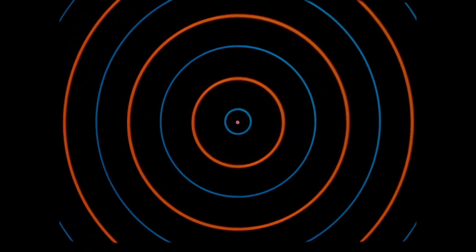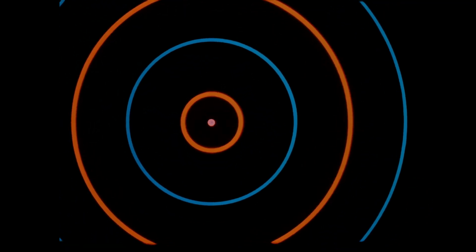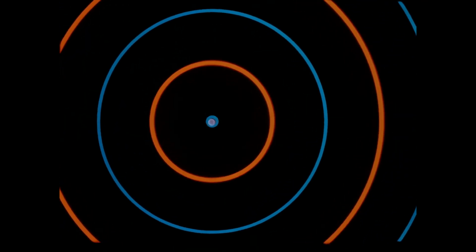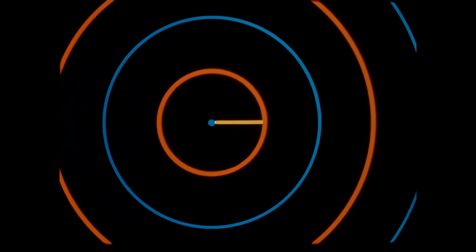To see how this is achieved, let us return to the omnidirectional pattern. Here, red represents the positive peaks and blue the negative peaks. The distance between two peaks of opposite polarity is 1/2 a wavelength. We will introduce a second dipole spaced 1/2 a wavelength from the first. If we feed both dipoles 180 degrees out of phase, we obtain this radiation pattern.